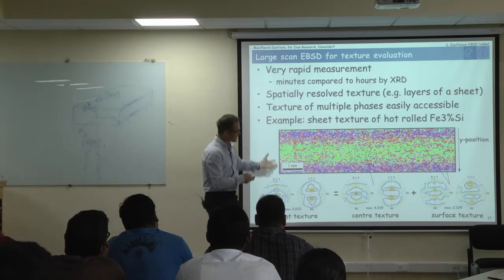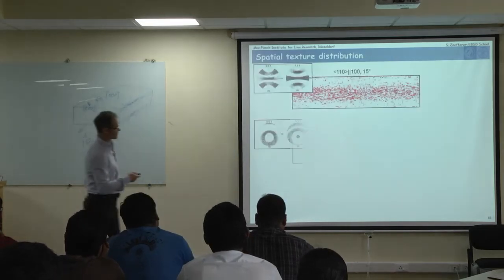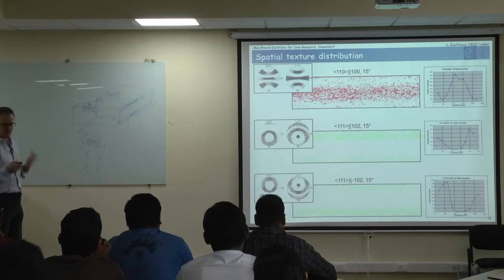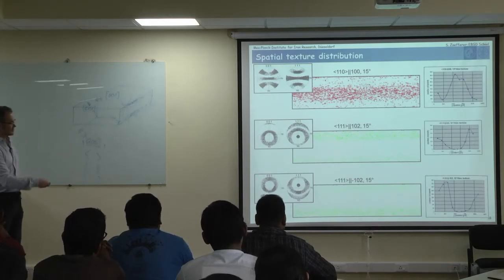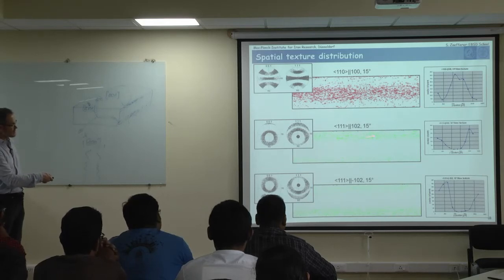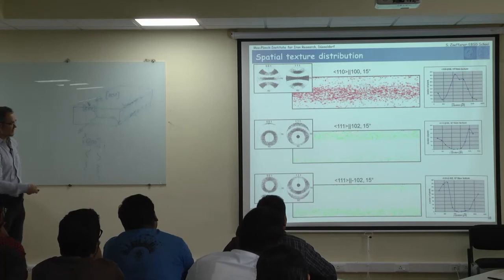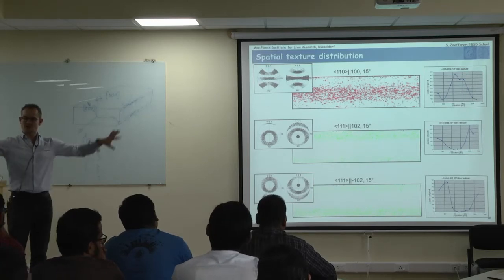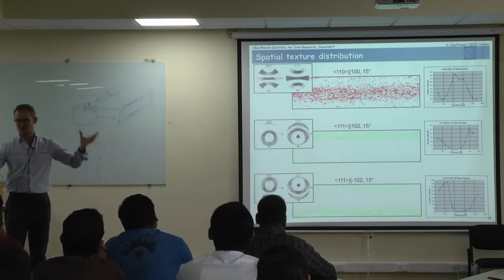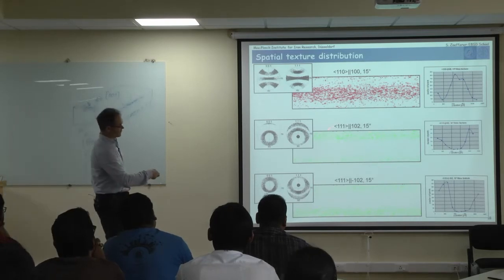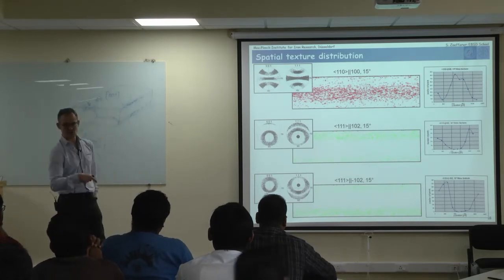And by doing a very careful analysis of these texture components, which I haven't done, but let's just make an example, you could tell there is a particular sort of shear going on in the surface and in the two surfaces. By changing the diameter of the rolls or the temperature of the rolling process, you could modify that. You could make it stronger or weaker.